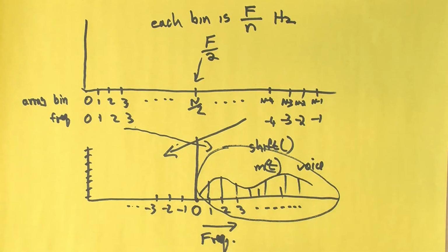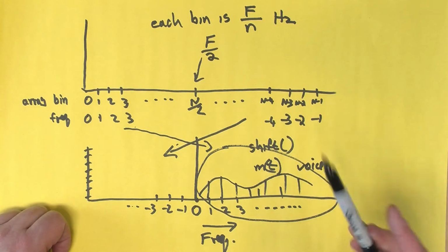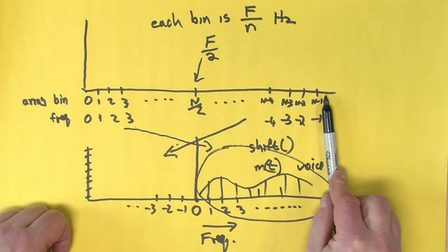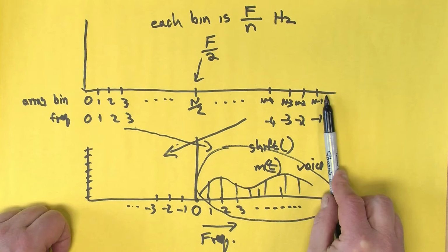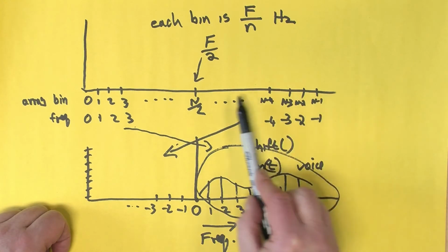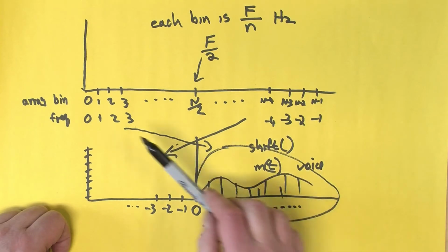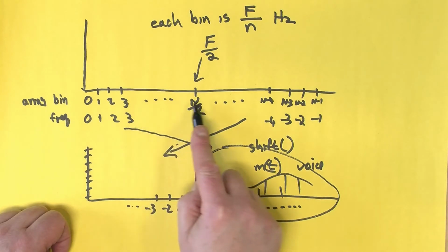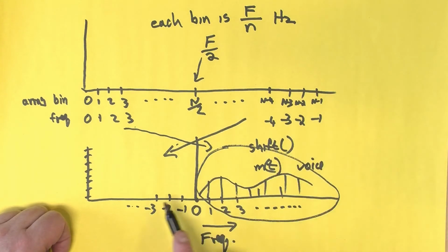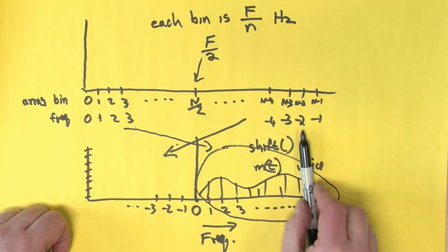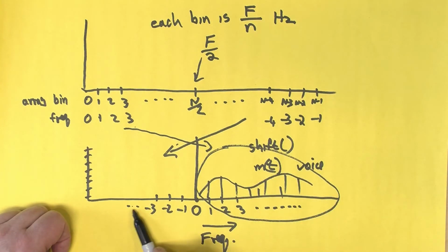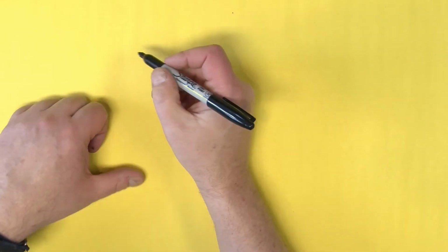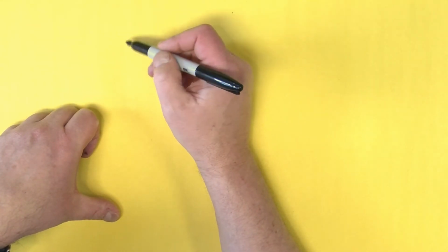So that's really all there is to it in terms of using most FFTs. The main thing is you end up with these funny negative frequencies, which might seem disconcerting. And as I said, we'll talk about it in the future. And you also end up with this sort of strange spectrum where you have a discontinuity between the positive and the negative numbers that you might want to swap to make them at least follow in a normal numeric sense from low to high.